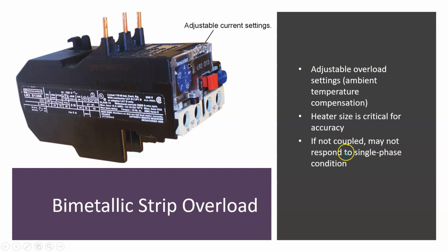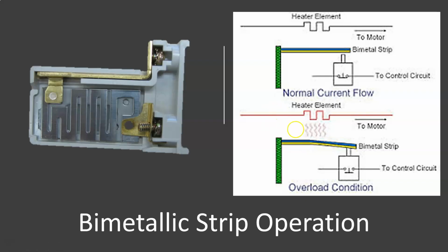If not coupled, it may not respond to a single phase condition. So you've got to watch out. Relying on single phase conditions can really be hazardous to your conductors and your motors. So you've got to make sure you couple them together, or they're not going to respond to that.